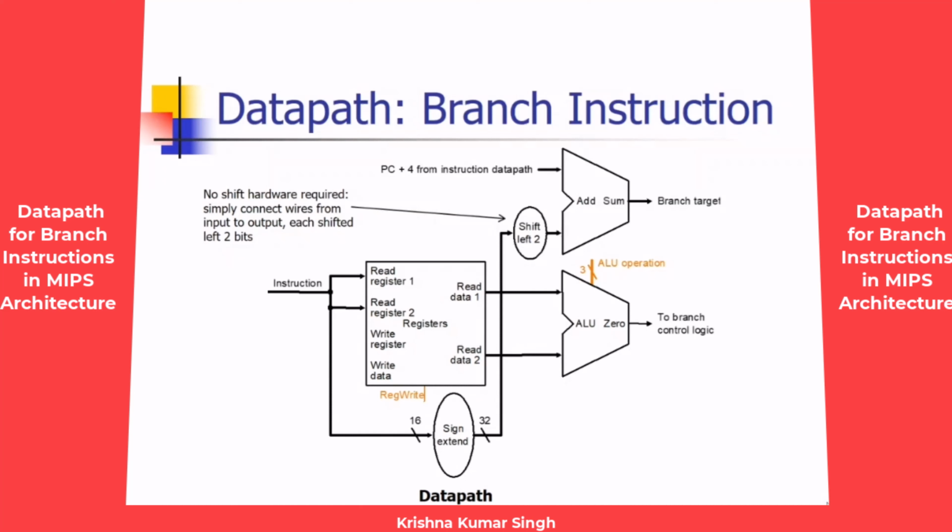Let's check the data path for the branch instruction. As you know, in the branch instruction, we check the content of two registers to see if they are equal or not equal, according to the branch equal instruction or branch not equal instruction. Then the control flows to the specific instruction that is mentioned by the label.